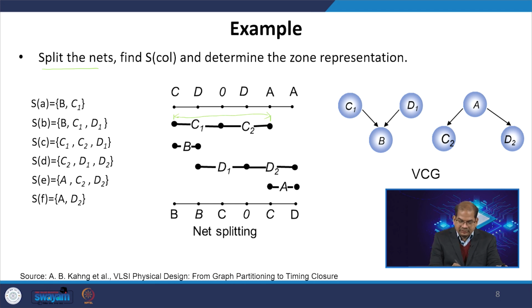So, if I use the complete track, then it cannot be accessible for the other nets. So, what I do is check where the pin is there in the vertical direction. Okay. So, there I will split the net. Here if you can see, I have a pin at this point. So, I split the net at this point, and the C net is divided into C1 and C2.